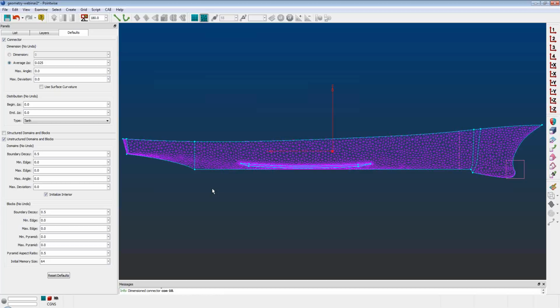And then as a second step, when you're done using that technique, you can tell Pointwise to recombine the TETs into prisms, so you get the flexibility of the 100% TET approach, get your boundary layer resolved meshes on your very complex geometry, and then you can use the prism recombination algorithm, that's what we call it.